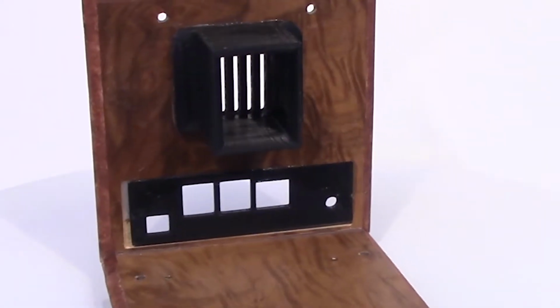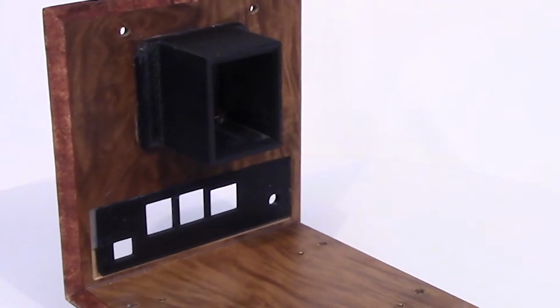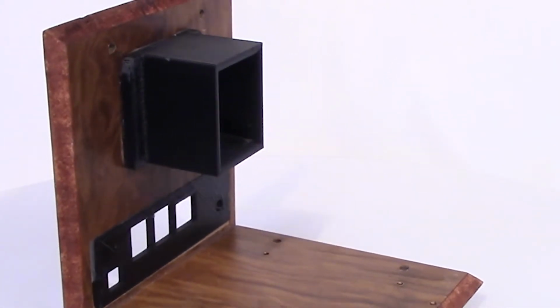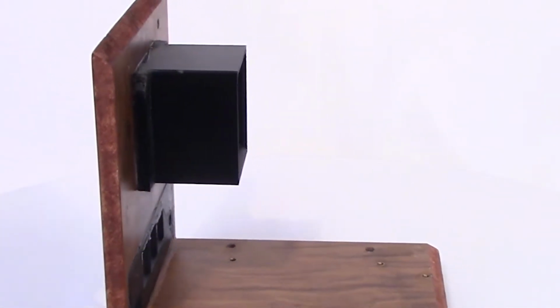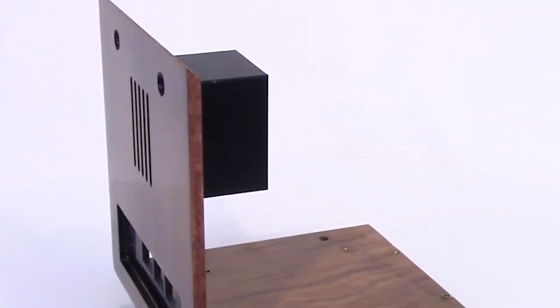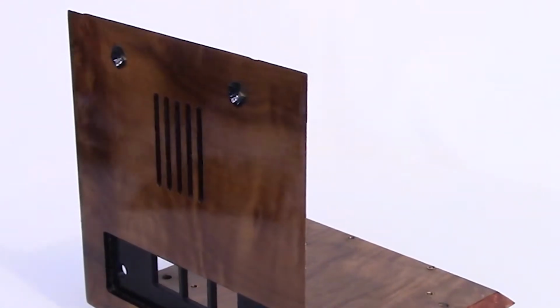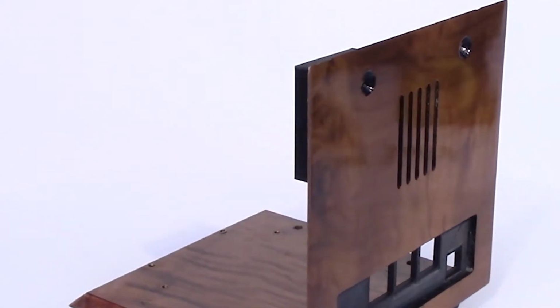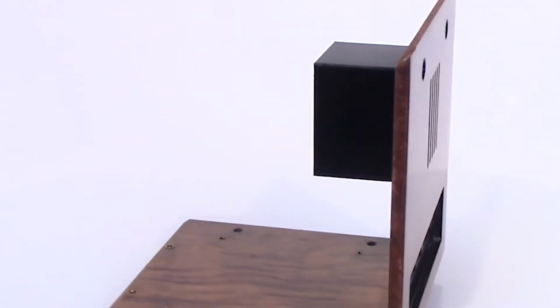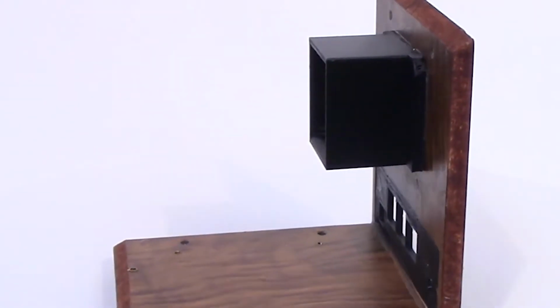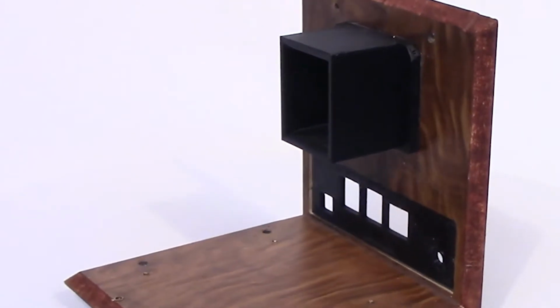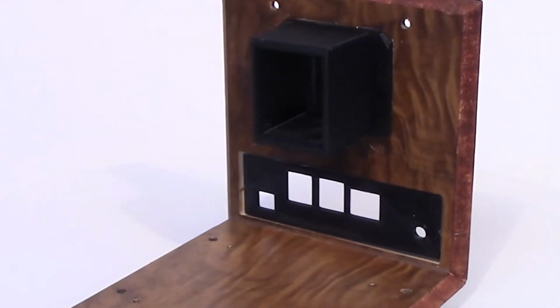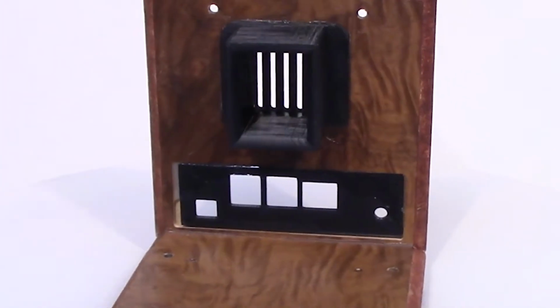The reflex port is another Muxall design that incorporates the rear air vent and ABS duct. This design has several advantages. First, the size and shape of the rear air vent slots and the duct length are tuned to extend the bass response of the system without adding to higher frequencies. Second, the duct extension reduces interference from drivers in an opposing configuration. Third, the air vent is large enough to keep the electronics cool without adding a fan or second air vent.